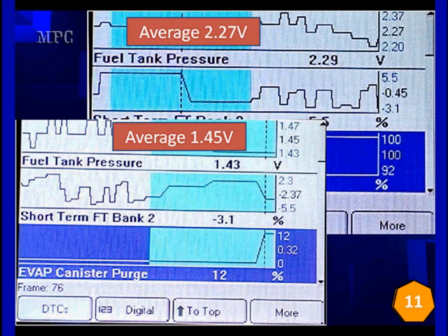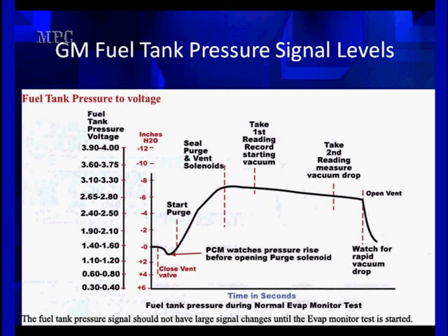Sometimes we get moisture accumulation in the canister that particularly causes problems in the wintertime. What you might want to do is take some very low pressure air, turn the canister upside down, and run some dry air through it to get this moisture out. Be warned, it's dirty, nasty, rotten stuff. What's wrong with the moisture, if you don't get it out, is it'll eventually deteriorate the carbon granules, the charcoal, and it'll start sucking it through the system and into the purge solenoid and block the purge solenoid. So restrictions get to be important.